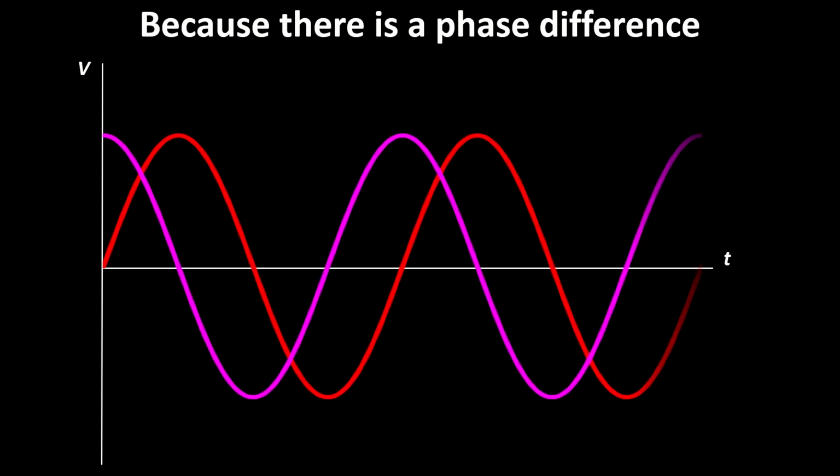So if we plotted resistor and inductor voltage, we get a similar sort of phase relationship, except the inductor graph is around the other way from a capacitor. The capacitor started at the bottom, the inductor starts at the top in this particular case. And now again, it's going to make more sense to explain this in terms of current. So current is in phase with the resistor voltage, so I'm just going to pretend that we're looking at current there. So we'll look at the relationship between current and inductor voltage.